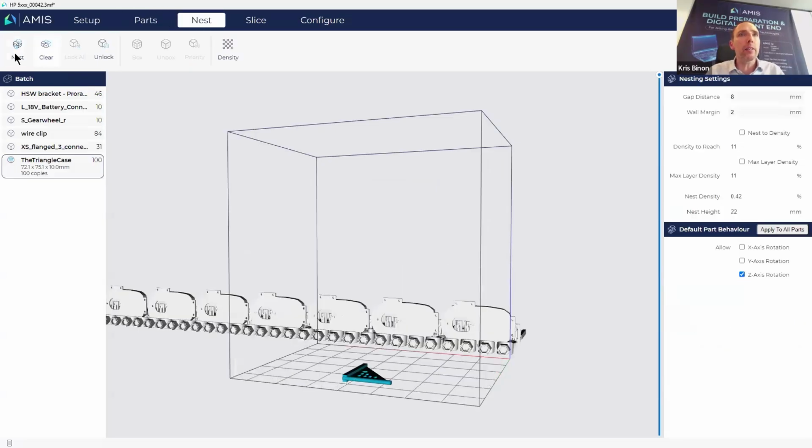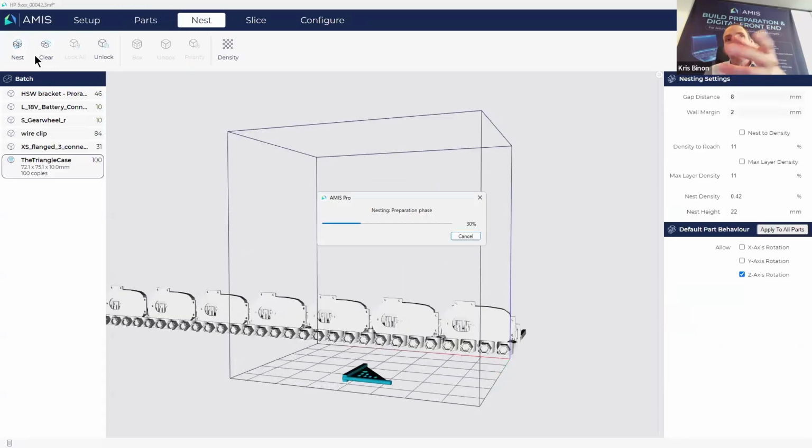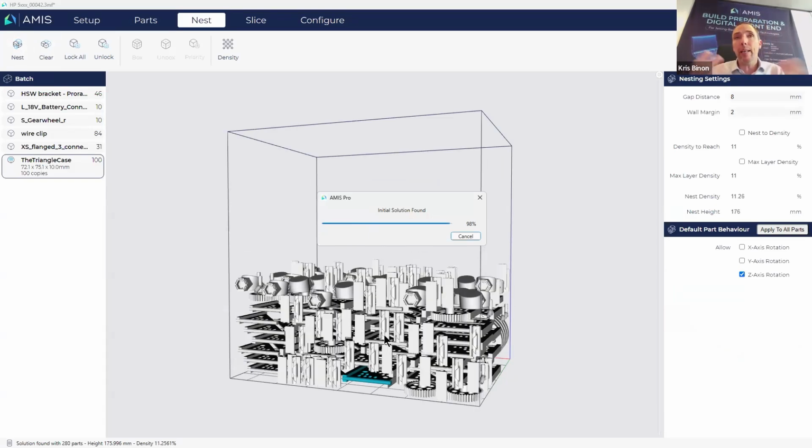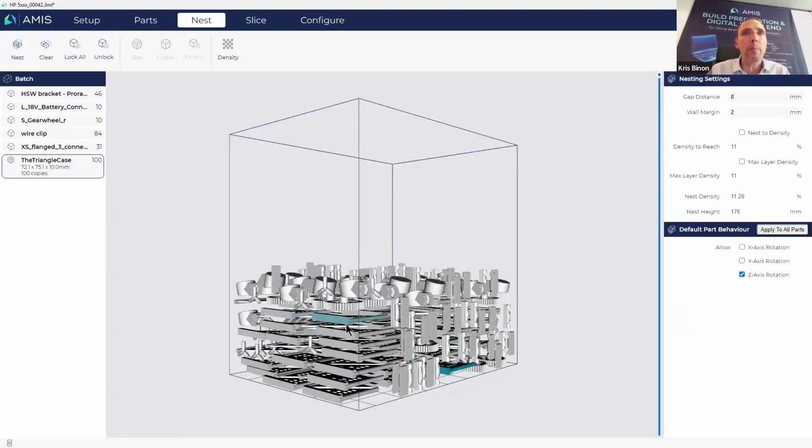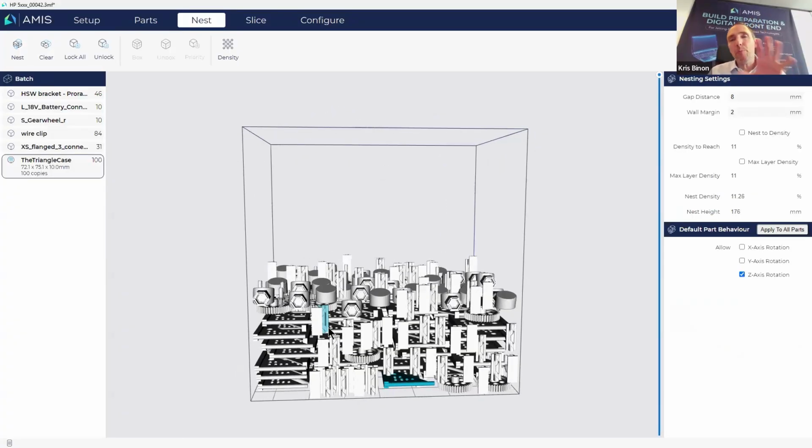And then I can clear to check if there's no collision. And then I re-nest and there is no problem at all. So I don't have any collisions there. So that you might do with a couple of parts, so that you actually change the Z position so that you, in that way, influence this first layer and that you make it a bit lighter.